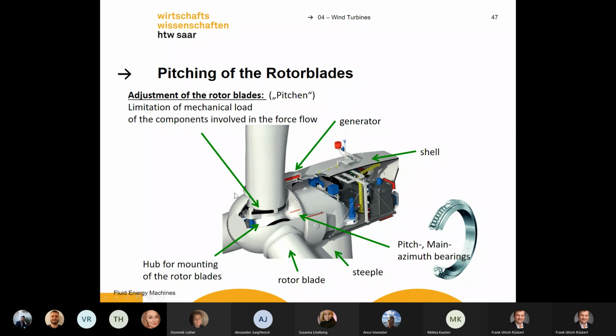This is a wing. You must rotate it, you must pitch it to fulfill the demands of the wind, and also to get less mechanical load, to brake the windmill a bit. And here is our engine. You pull this rubber band, then you can pitch the blade.